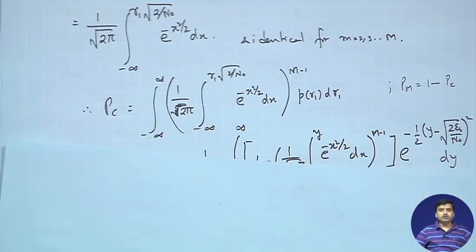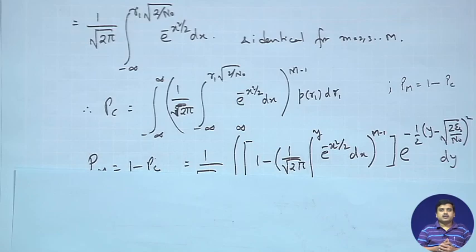So, what we will do in this particular case is, instead of calculating the exact expression of error, we will use the results which can be found by solving this particular expression, and will focus on the performance of such scheme, that is error probability versus the Eb by N naught, or the signal to noise ratio.